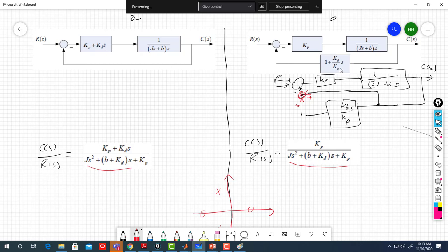Do a design of proportional plus velocity feedback. And this you don't find in your PID function that you get when you install the library, just the inherent library. You don't have this variety of options. So if you want to make something better, you need to make the library yourself and have a feedback derivative control.